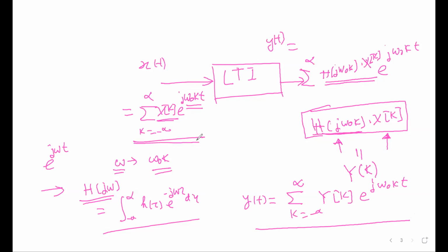You see that when we express our periodic input x as an exponential form of Fourier series, then by the concept of our transfer function, we can easily find the Fourier series of our output, yt. So your yt will also be periodic and the Fourier series is there, and the Fourier constant yk would be equal to the multiplication of the transfer function at that harmonic frequency with the corresponding value of the Fourier constant of your input. So your yk can be determined in this way.